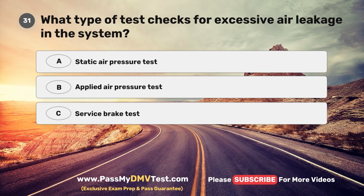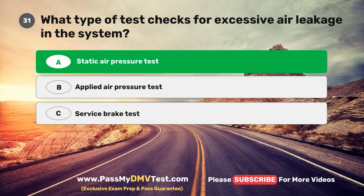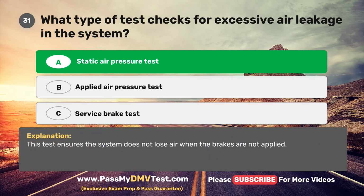Question 31. What type of test checks for excessive air leakage in the system? A. Static air pressure test. B. Applied air pressure test. C. Service brake test. The correct answer is A. Static air pressure test. This test ensures the system does not lose air when the brakes are not applied.